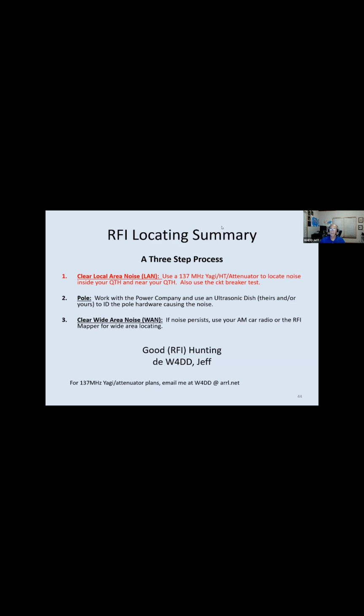Yeah, some of the high voltage lines, the like 400 kV lines, they have special tools they use, like that viewer, to tell them if they have it cleaned off enough to be able to go on to the next insulator. But those things, I've never found one of the high voltage lines causing noise. It's almost always the 7 and 14 kV distribution lines. A friend of mine supposedly had one that was causing a problem, and they said, well, in a year we're going to turn that line down and wash the insulators and check all the parts.